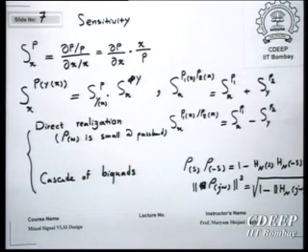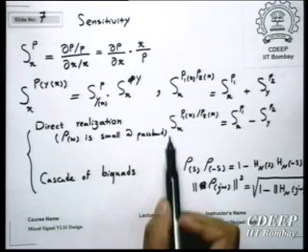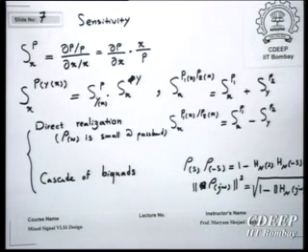But what will happen in the transition band? In the transition band, there is a rapid increase in rho. Therefore, that transition band will be sensitive now. Therefore, if we are optimizing for minimum sensitivity in the passband, there will be a problem with the transition band. Now, what about the biquad? If we make a cascade of biquads.